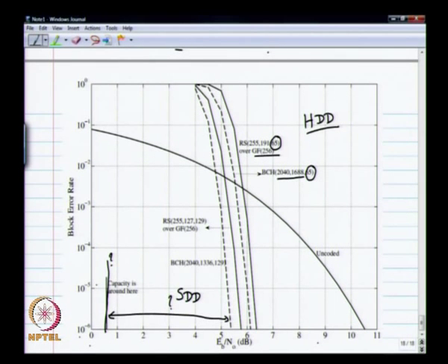There is also block error rate, no? So this is slightly different. If you compute bit error rate, something very different will happen. Block error rate also is a misleading reason why this weird curve is showing up. Bit error rate will be slightly different. How do you compute bit error rate for a bounded distance decoding? You can't sometimes analytically compute. It's very difficult.